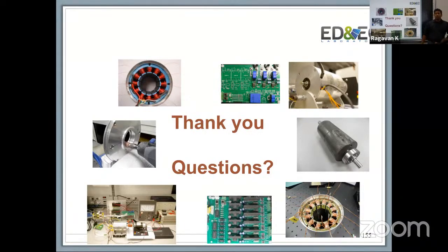So no, not this many. They only have, like I said, oftentimes if you're doing a prototype, a couple of search coils that they will provide to you. It's meant to be a probe. It's meant to be a field probe that gives you information about how the flux is flowing in the system. So typically they wouldn't, and that was fundamentally the challenge that they identified, that we would have to crack open the motor, and therefore we don't want to do this.